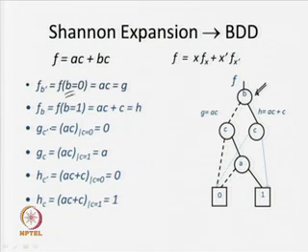That means I am using the Shannon expansion on the variable c, and finally, we are going to apply the Shannon expansion on a. So, you just see that now I am having b, c, a. So, this is another reduced BDD on this particular three variables a, b, c. Now, again you just see that I think it is a reduced one, you cannot apply any more reduction in this particular thing. So, we are getting a reduced BDD.